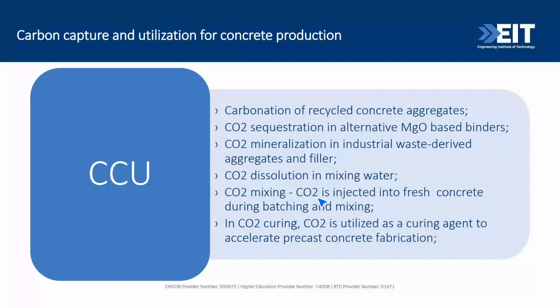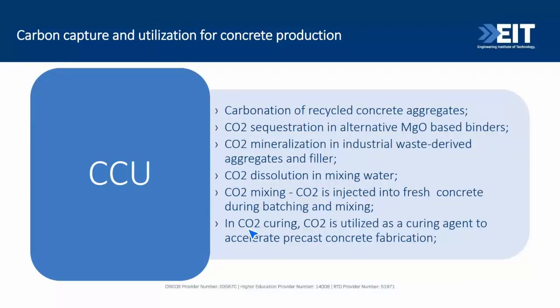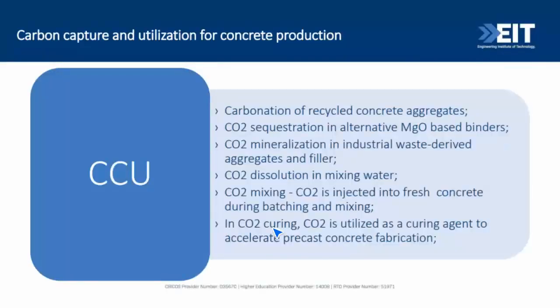And in this case, in concrete mixing, we have some good results available in the literature showing that carbon dioxide injected into the fresh concrete during batching and mixing can also improve the final mechanical properties. And because concrete is a composite material, we have the ingredients, we have the mixing of these ingredients, and then we have the curing process. When you think about prefabrication, this can be a viable alternative, with carbon dioxide utilized as a curing agent to accelerate precast concrete fabrication. What I'm trying to do here is just summarize what we have available in the more recent trends in the literature around this topic.